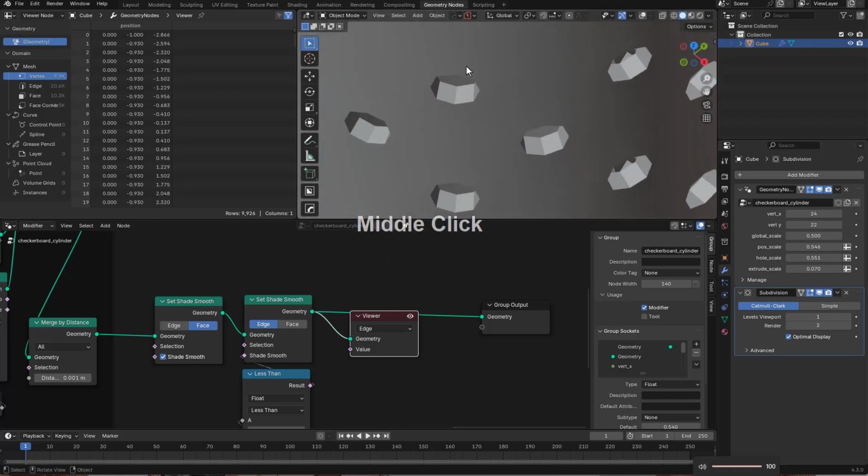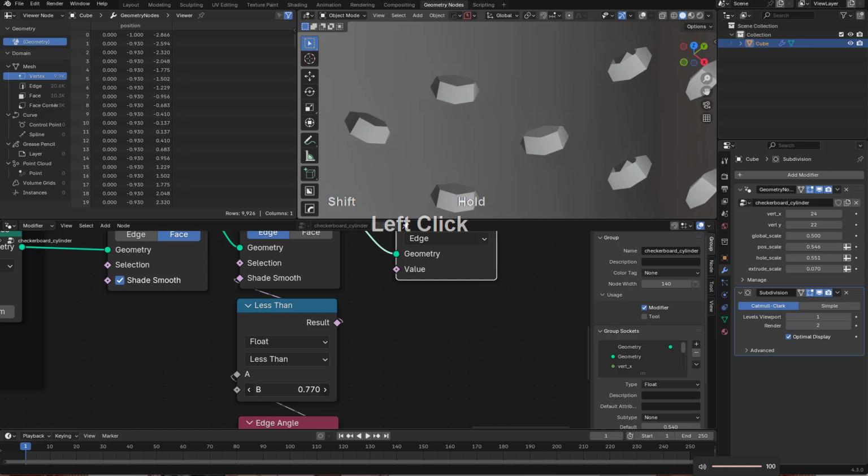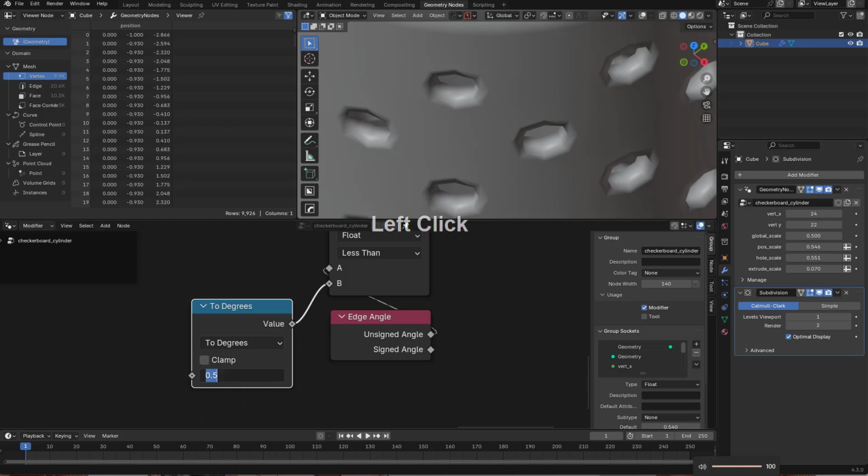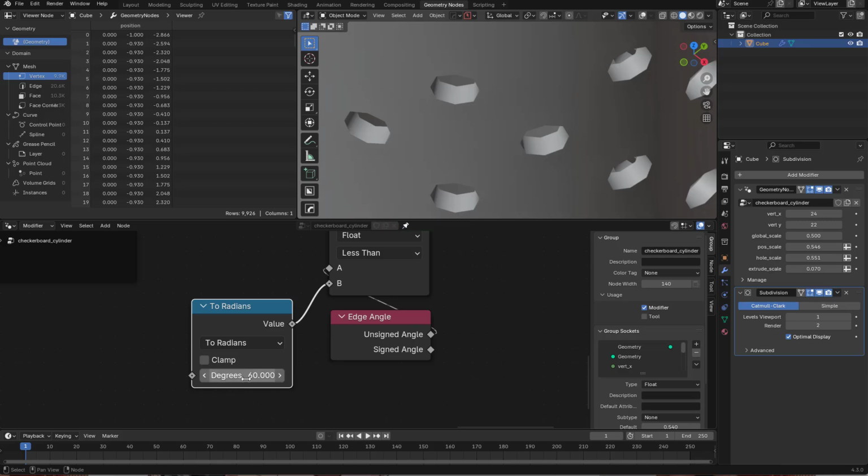And it's almost there. So now we got it smooth on the outside, but we still have a little bit of faceting on the inside, meaning we need to get our angle just right. Instead of playing with the, I believe, radians, we could also change this to degrees, and once it's degrees we can put in an actual number like something like 30 or 60, or is it 2 radians? My mistake, 2 radians, 60 degrees, 2 radians.